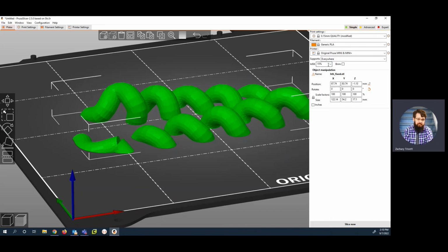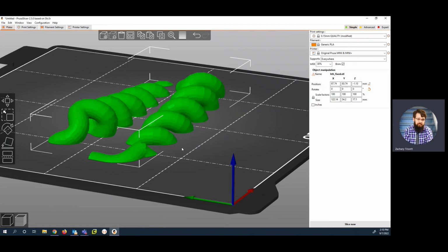And then there is infill, which this being a solid, it's not going to print it completely solid. It's going to print it partially hollow. That is what the infill is. So the solid portion of your model can be 20% infill or 40% infill. So depending on what you want for your design, you're going to choose the best option for that. 20 to 30 is recommended for most things. So we'll just go for 30. And then you'll want to select brim.